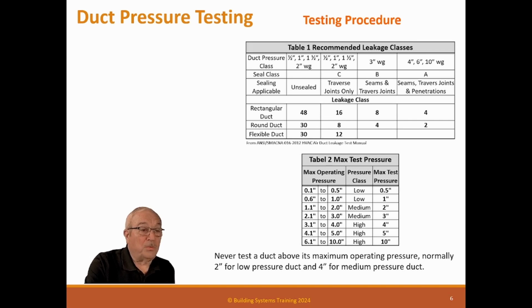I said, that's a 20-inch blower. That blower is capable of blowing 20 inches of pressure. So no wonder you blew the duct apart. He said, but it's too small. No, pressure doesn't matter by size. It matters about the type of fan it is. So when you do these tests, you need to stay right with it. You don't want to walk off. So always test at the highest pressure or it'll damage the duct.